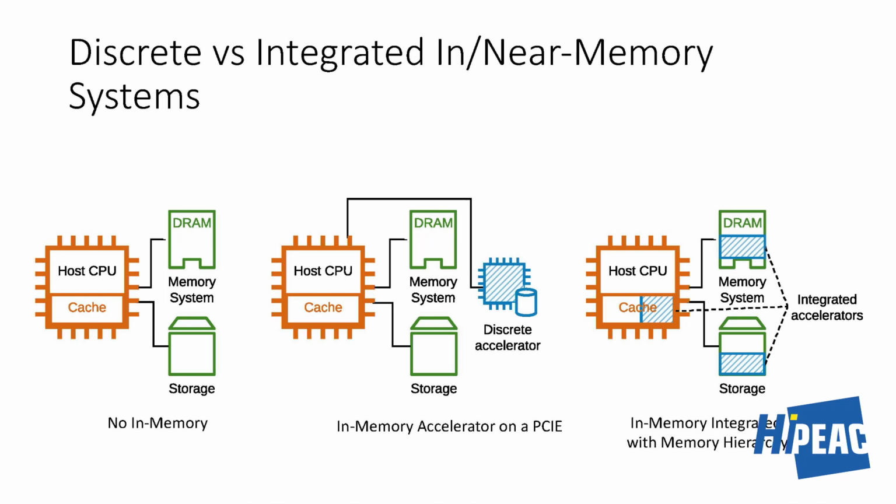But at least for SRAMs, we have gotten it to the point that it's very low overhead in terms of area. So two answers to it. One is raw area overhead. It varies from 3 to 30% depending on the memory technology. Dynamic overhead of how much cache you can use, I think, is not a problem, because when you are not using it in accelerator mode, you just use it as a memory.